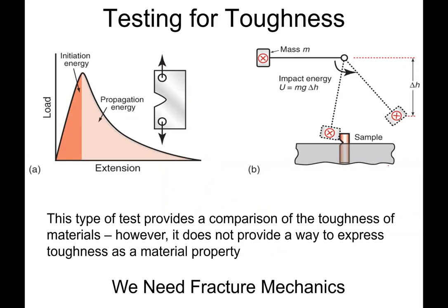Okay, so with the Charpy impact test, again, make sure you watch that video. What we were looking at was the energy to fail a sample, how much was absorbed in the sample during the process. It works very well as a quick test. You can see ductile to brittle transitions as the temperature is changing on the sample, but it doesn't give us quantitative numbers or really define a material property.